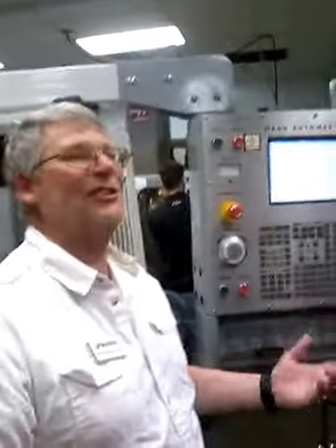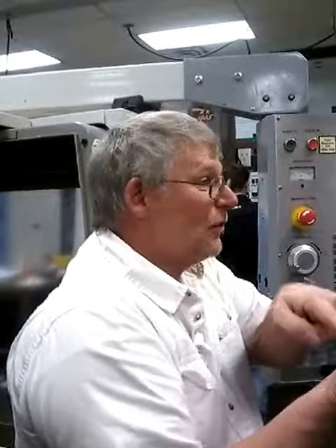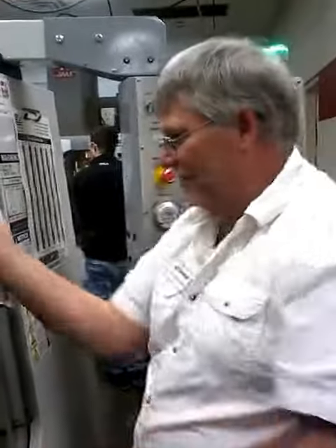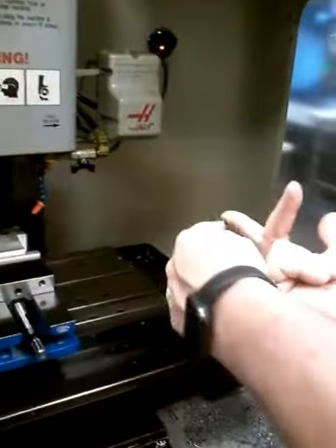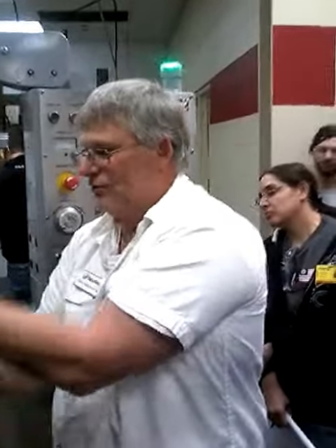When we start talking positive and negative, I'm going to do this. Everybody's an adult here, right? You know what I'm talking about. This is our right-hand rule. When I am standing at the operator's location, looking at the machine, and I do the right-hand rule, guys, this is all of my axes positive direction. This is X positive, Y positive, and Z positive.